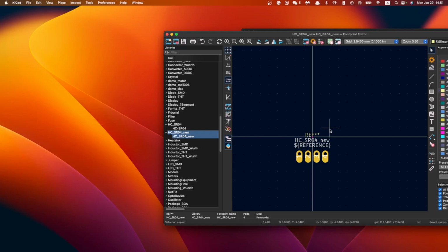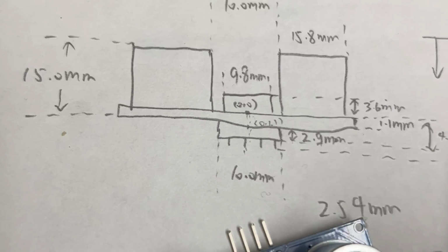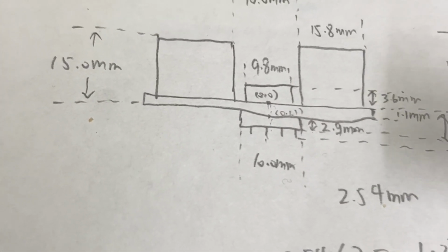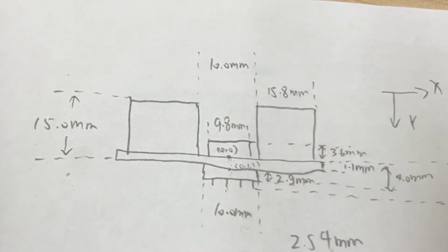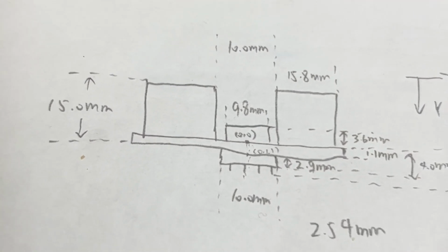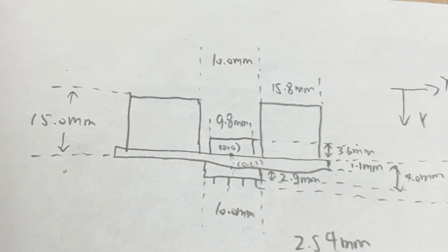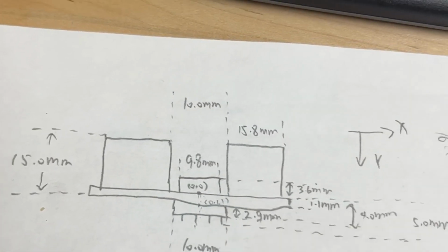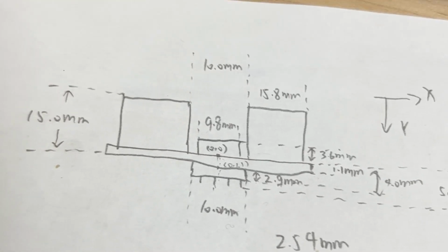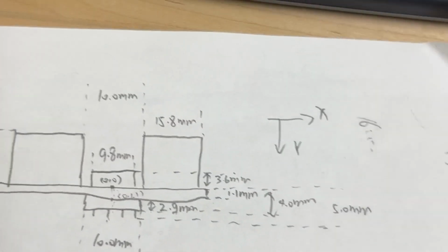For example, I need to create these rectangles here to make sure that the space this device is taking up on the PCB board will be correctly showing up on your PCB editor, and it will also be printed out as silk screens on your actual PCB. So in that case, you will avoid overlaps on your PCB board, right? You cannot have overlaps of devices on your PCB board.